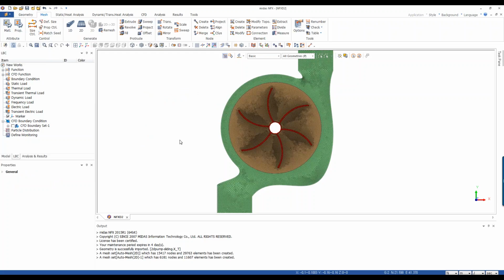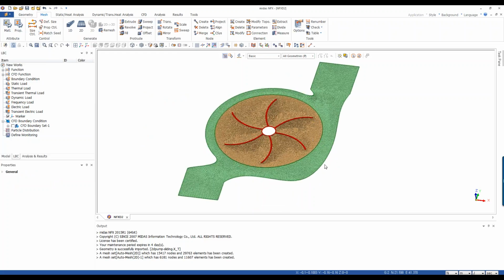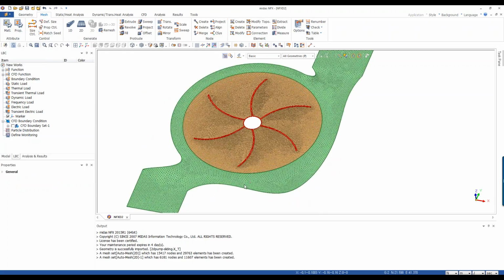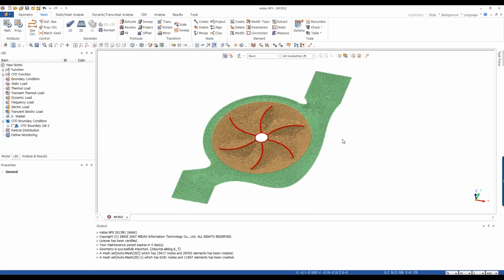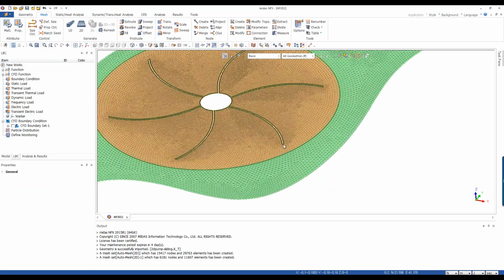So now that I have done that, there's one additional thing that is very important, which is that you have to check the orientation of the elements. This is special to 2D type of modeling for that rotation, because if the elements from this face are not in the same Z orientation as the body, you will have some problem during the simulation.